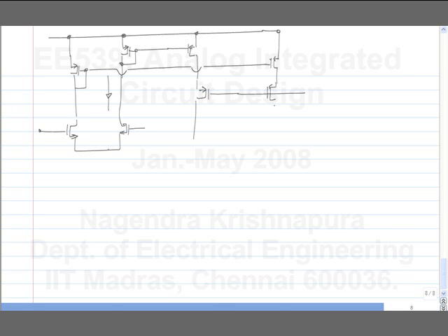Then what do I do? Let's say I have I0 by 2 plus ID. I0 by 2 plus ID, and let's assume identical current mirrors. Sorry, minus ID, of course. So now here I have I0 by 2 minus ID and I0 by 2 plus ID. It's as though I use the PMOS differential pair. Okay, I have just changed the direction of the current. Now what do I do on this side? So I can use an NMOS cascode. Okay.